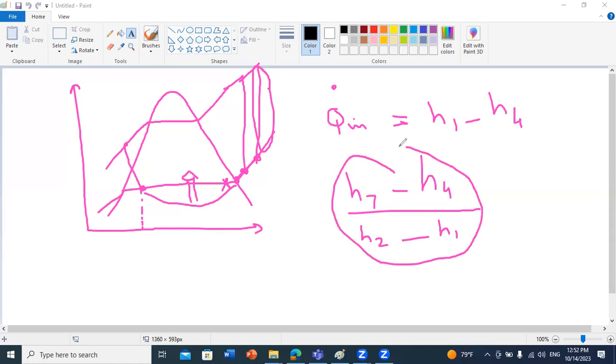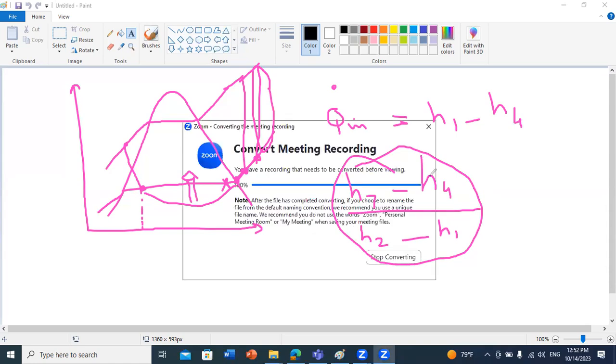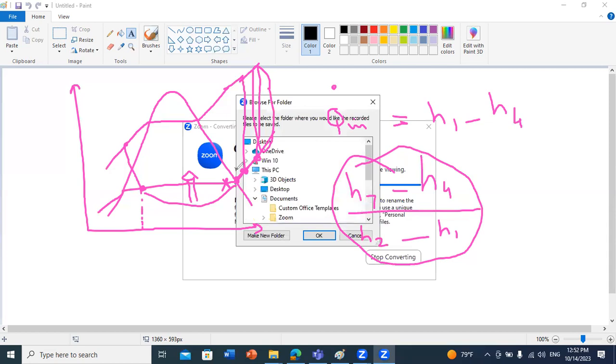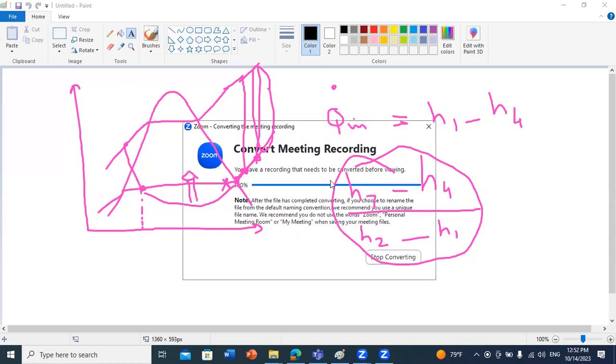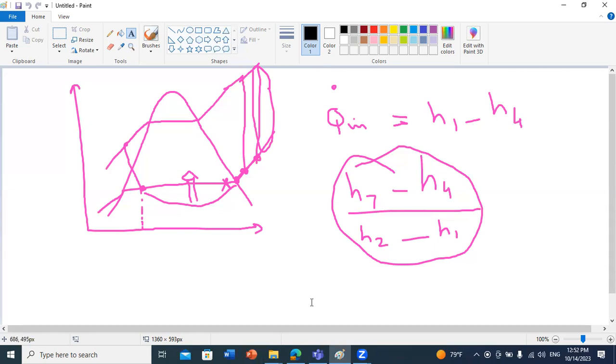This is why whenever we want to do the design, we try several configurations to determine the optimal case. So what is the best point at which we should leave the evaporator in order to enter the compressor and get the best efficiency? The majority of systems will require optimization techniques in order to select the optimal point at which to exit the evaporator and enter the compressor.